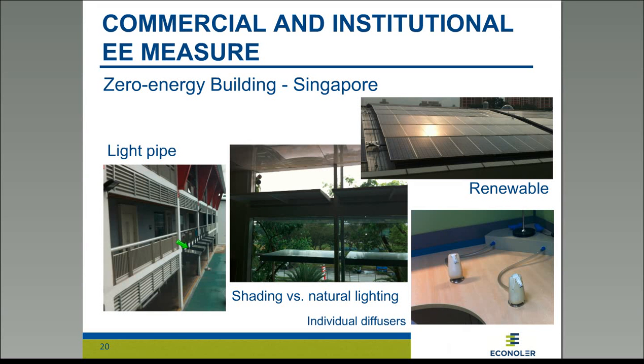So that's the collector here outside of the building that will bring the light inside the middle of the rooms through a mirror-coated duct. There's a shading device. Again, the shading devices are to reduce the heat gain during the summer period, but at the same time, they reflect part of the sun lighting to the ceiling of the rooms in order to reduce the artificial lighting.